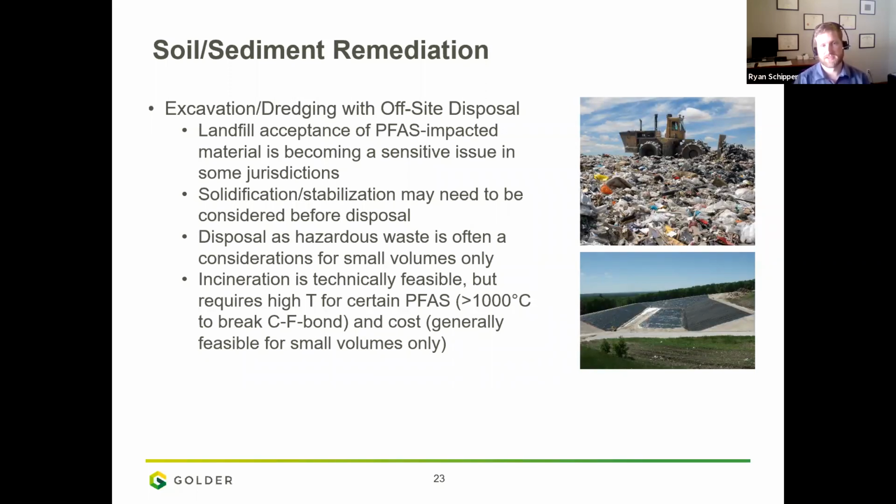Part of it too is there's not one temperature where you're magically destructing all the PFAS. There are different temperatures for each one of them. Another concern is that when you do destruct those PFAS compounds, a lot of times you're generating an acid which can cause issues with the materials of construction of the incinerator. There are some high-temperature incinerators that can deal with this, but you can't just send it to any incinerator.